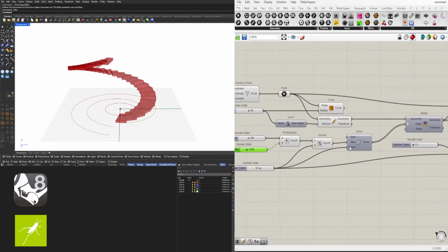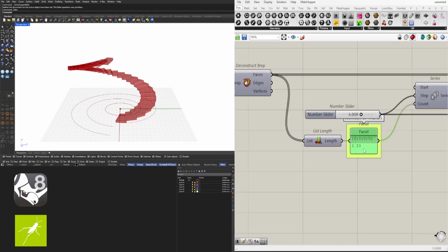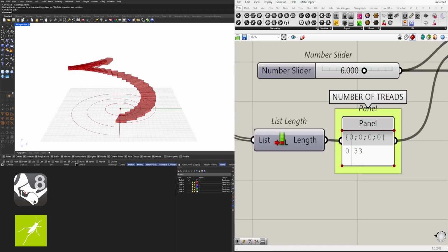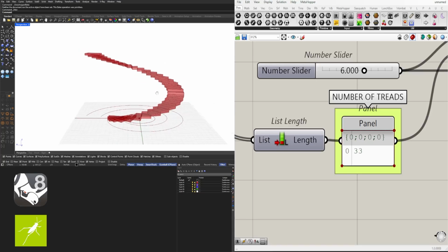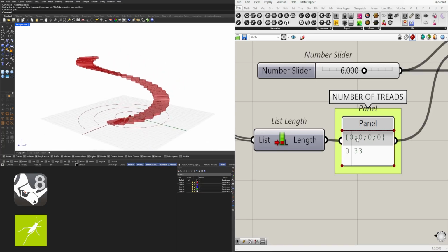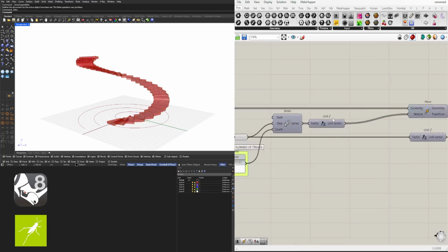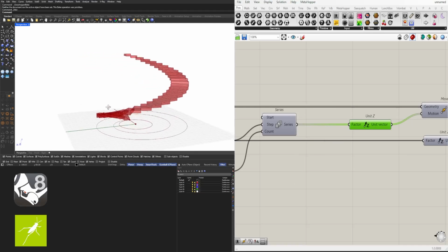Now here, the issue is that when we have too many treads, so here we have 33 treads, if we have more than 20, we're going to need a landing at some point. And so that's going to be the next part I'm going to show you, is how to take all of these steps, because they step by 6, how to introduce at the 20th tread a landing.